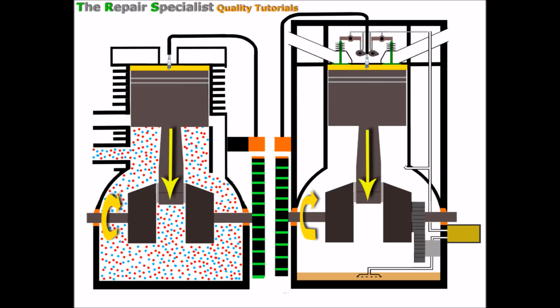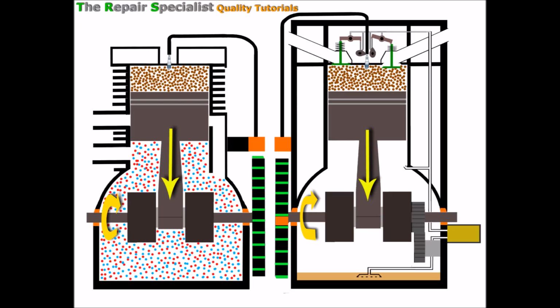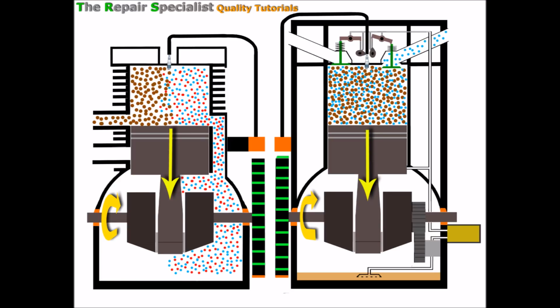That again generates enough power to force those pistons back down and leave behind in its wake all those exhaust gases. And as before, with the 4-stroke, the exhaust valve opens slightly as the piston lowers to bring some of that fresh air in to whirl round with the exhaust fumes, which helps to dilute them and helps clean the cylinder, and also helps the piston to lower that much better without it being caught in a vacuum. And on the 2-stroke, as we know, there are no valves to open, and there may well be a small vacuum for a very small distance of its travel. But as soon as we go a bit lower and open those ports there, any vacuum that may build up in there will no longer be a problem.